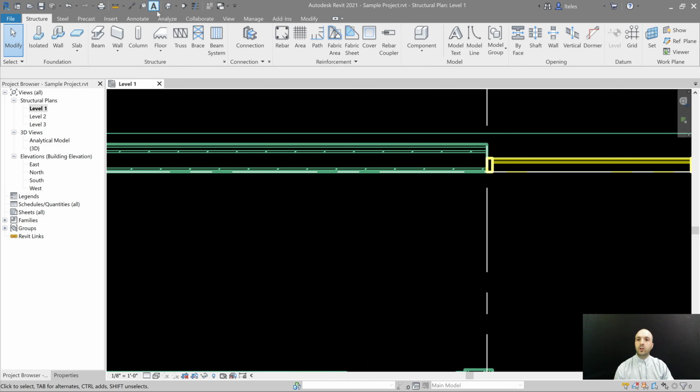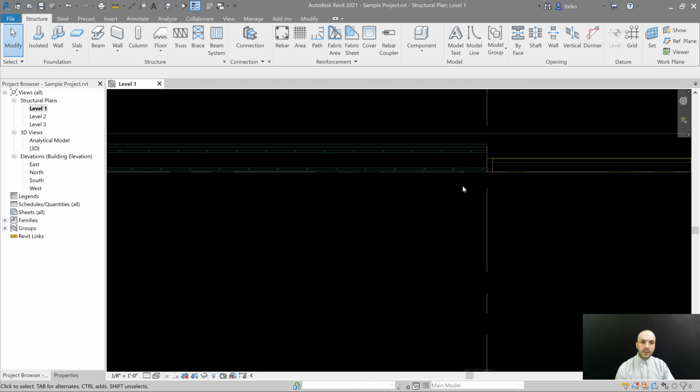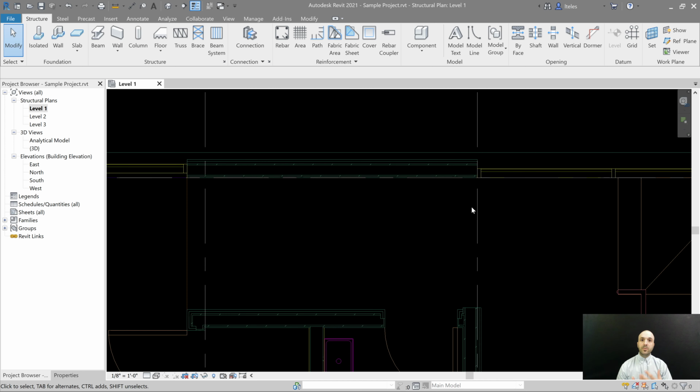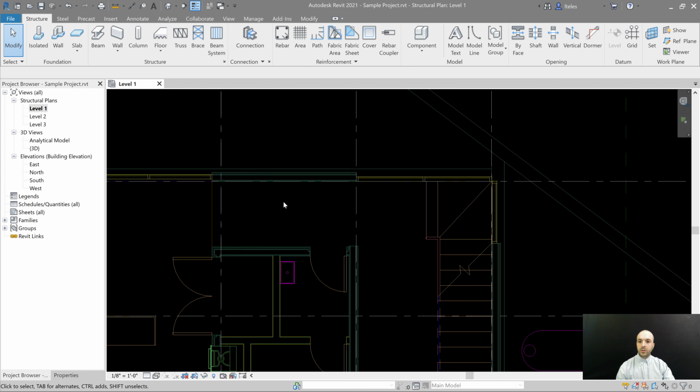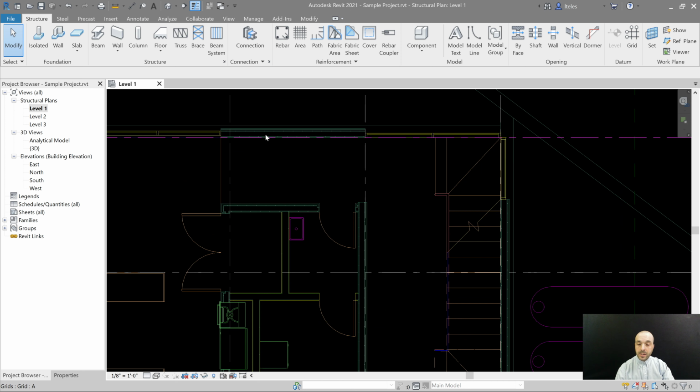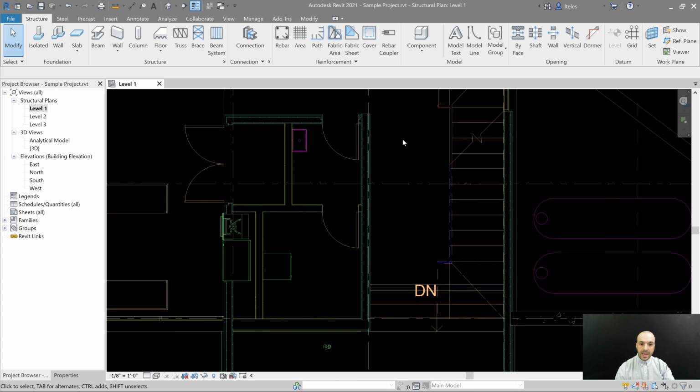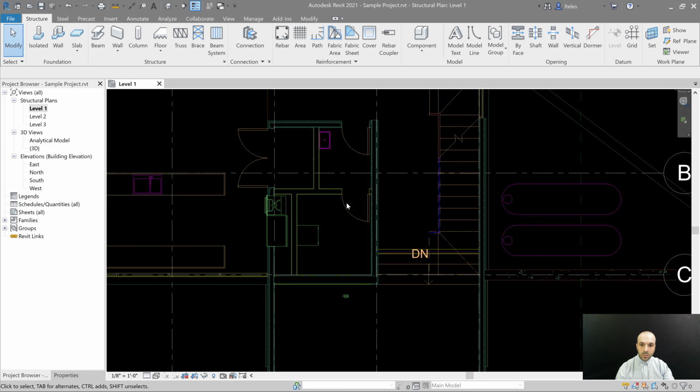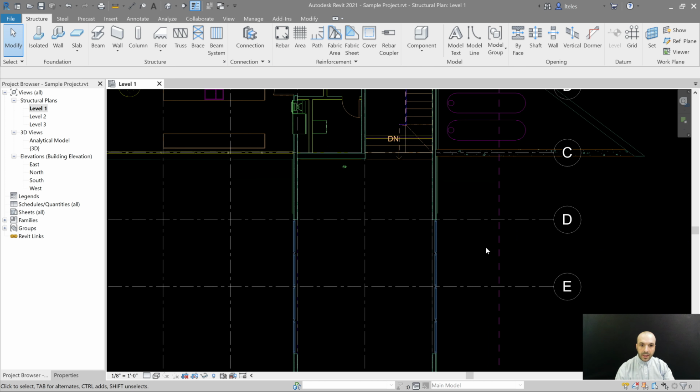So at the top on your quick access toolbar, go ahead and hit thin lines, and we should only see lines now, okay? Now let's assume that in our company's communication with the architects, they've come to the conclusion that this exterior wall right here needs to be concrete, and these two interior walls need to be concrete, and